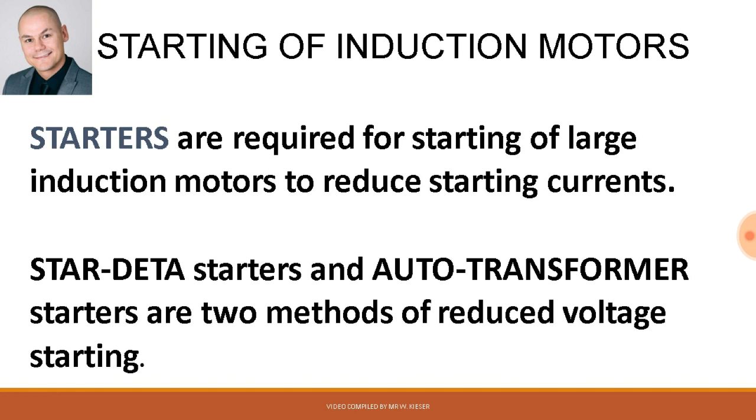Starting of induction motors. Starters are required for starting large induction motors to reduce starting currents. Now, in terms of reducing voltage, there are two types of starters we can use. A star delta starter and an auto transformer starter are two methods of reduced voltage starting.